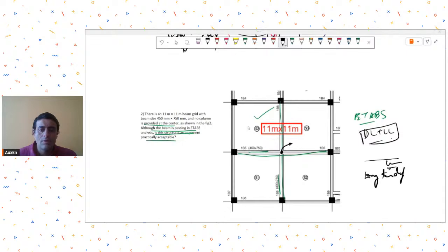Remember that point. Accordingly, design your beam depths and slab thickness. So whatever deflection you are getting, if it is the short term elastic deflection that we usually get, and you have not run any cracked section analysis, then remember that your actual deflection for creep plus shrinkage will be almost 1.5 to 2 times, sometimes as high as 3 times, the deflection that you get by normal dead load plus live load.